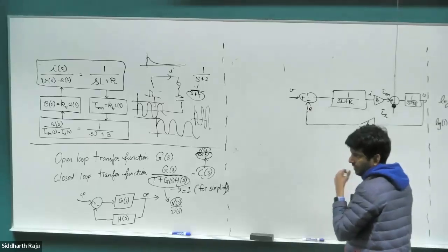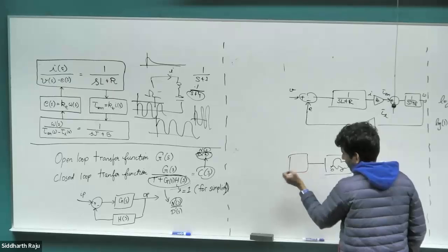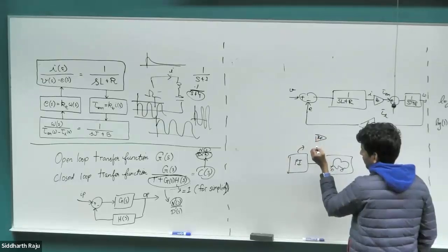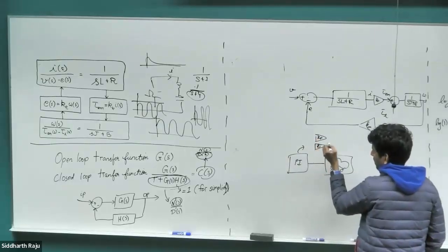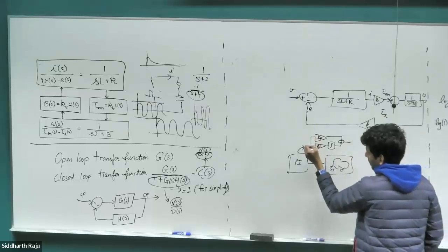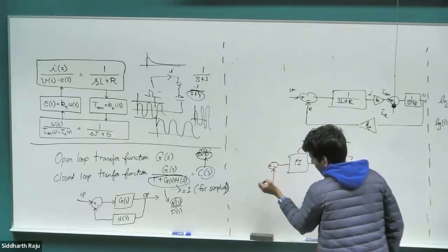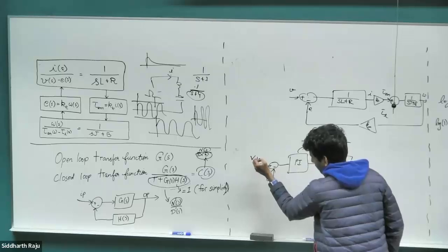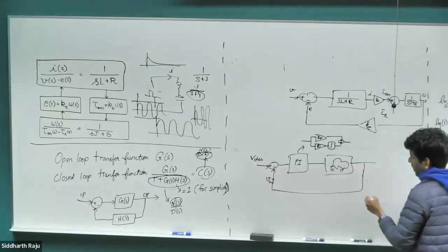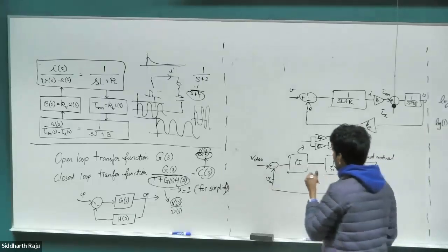So when we looked at the case of the driving example, we had our car, and then some PI controller. And this PI controller itself is some gain value Kp, and then some integral gain Ki with an integral output, and then these two summed up together. Right? This is what is inside that box there. And what comes to it is the error between our desired velocity, V desired, versus V actual, coming from a speedometer.